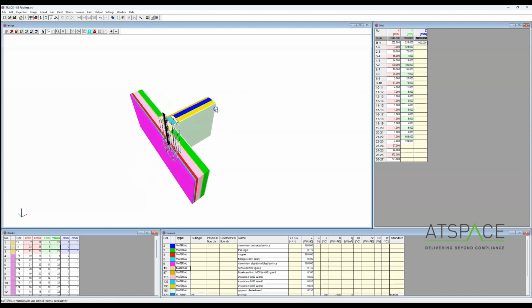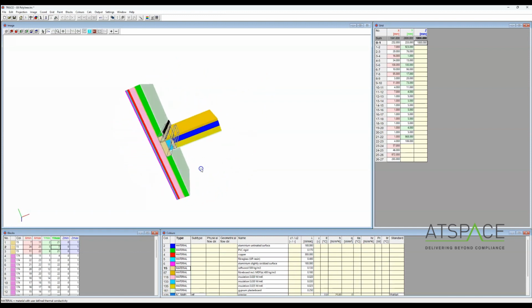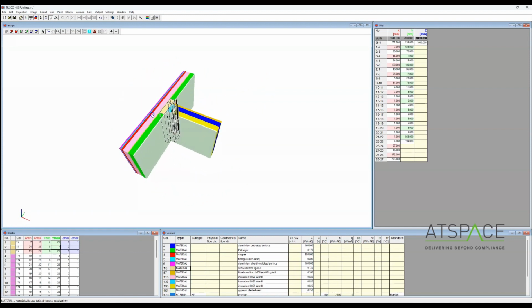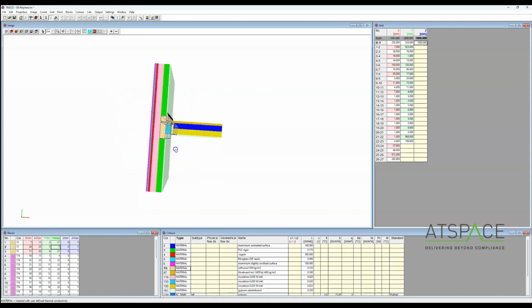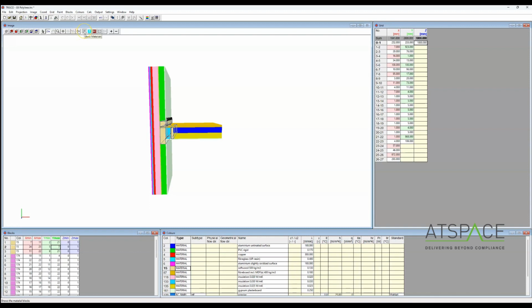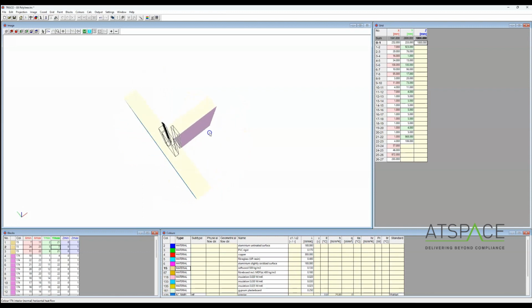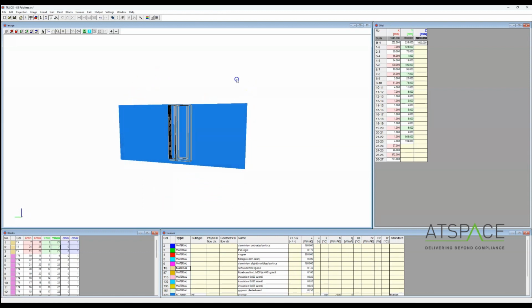And we can see the materials here are being displayed, but those boundary conditions, which I mentioned earlier, you can't really see them here, and that's because on this toolbar up here, it's selected to show materials. If we move along here, we can show boundary conditions. If I click that, it will show you all the materials have gone one color, and then the boundary conditions are all different colors.